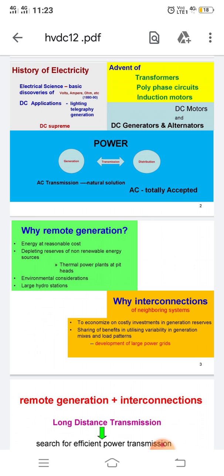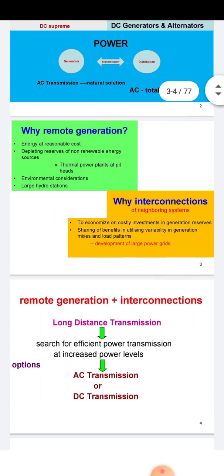Until the 1970s, the converter stations utilized mercury arc valves for rectification. The successful use of thyristors for power control in industrial devices encouraged their adoption in HVDC converters, through the development of high power semiconductor devices. Then we must concentrate on the comparison of AC and DC transmission.